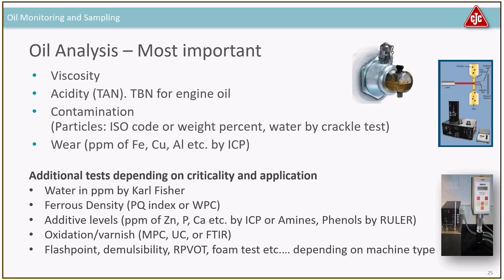And obviously there are a lot of other tests depending on the machine type, so you will have flashpoint for engines, demulsibility for steam turbines, RPVOT, oxidation test for turbines, foam test for gear oils, and so on.